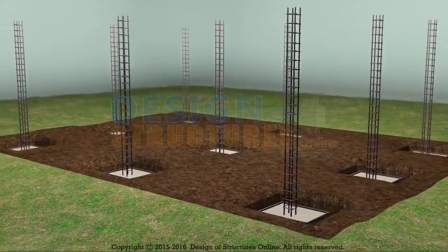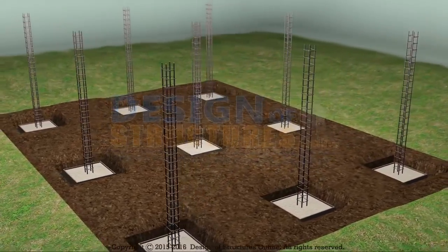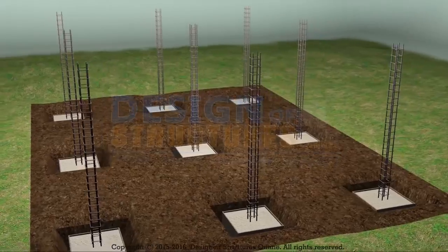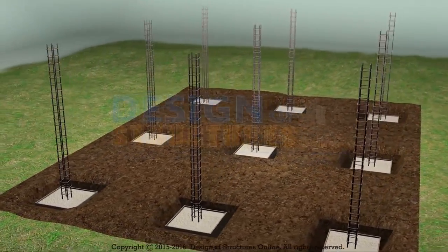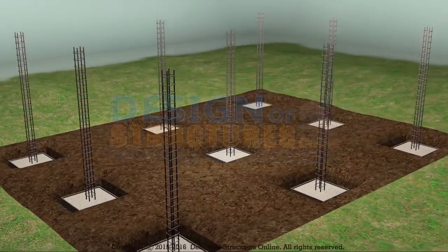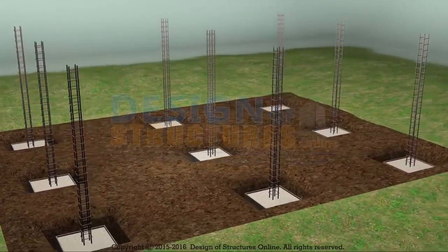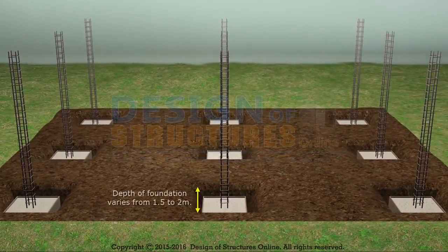It is very necessary to check the levels of the foundation before concrete work. Depth of foundation varies from 1.5 to 2 meters.